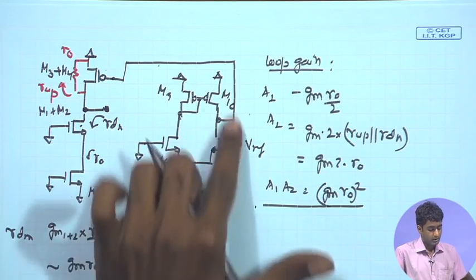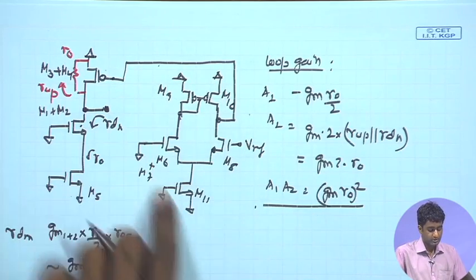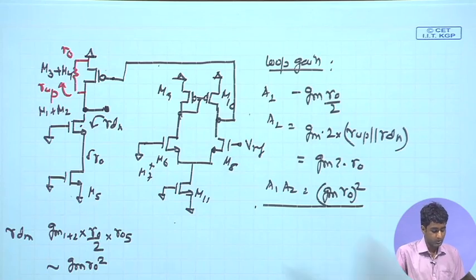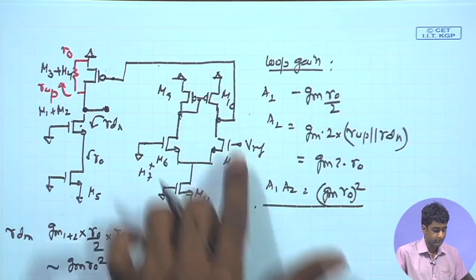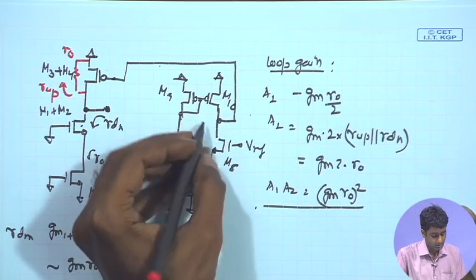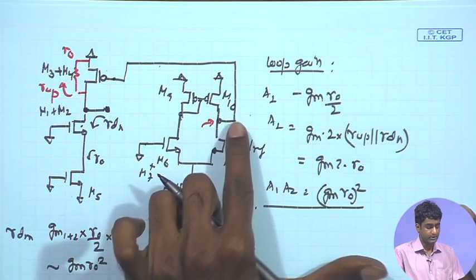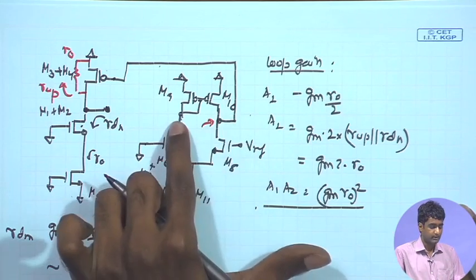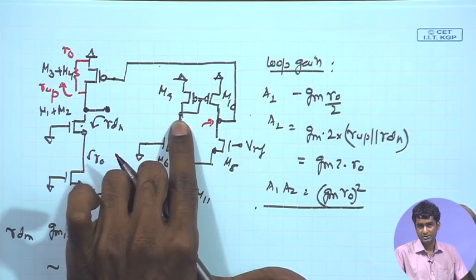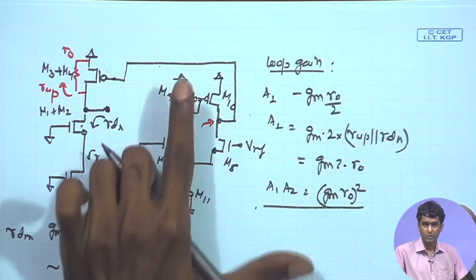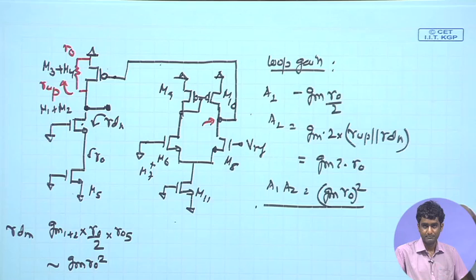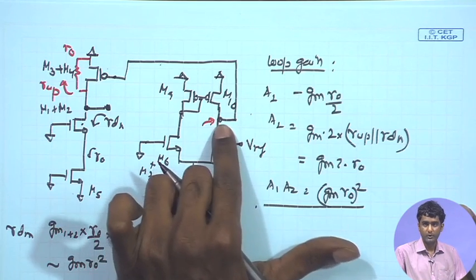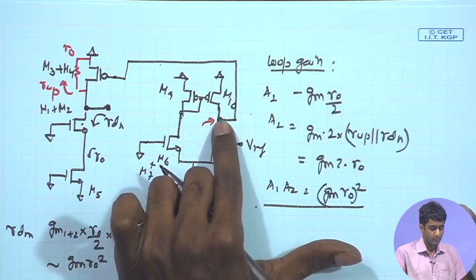So, from our previous discussion on the differential amplifier with current mirror load, we know that this particular amplifier offers a critical pole at the output node, because here the overall impedance is highest, that is ro by 2. At the other node, the overall impedance is significantly smaller, it is just given by 1 upon gm of the direct connected device. As a result, this is the one which is going to offer critical pole for the first stage.